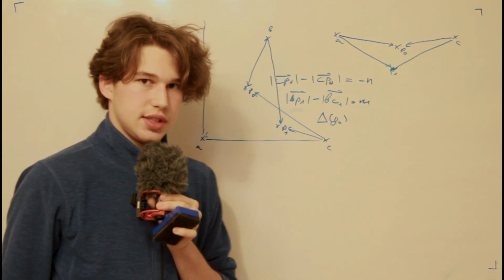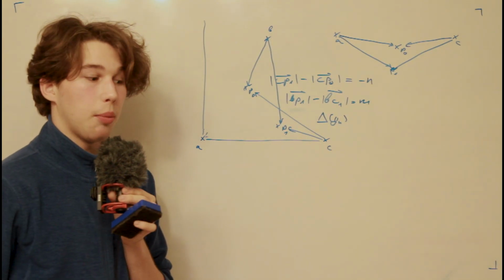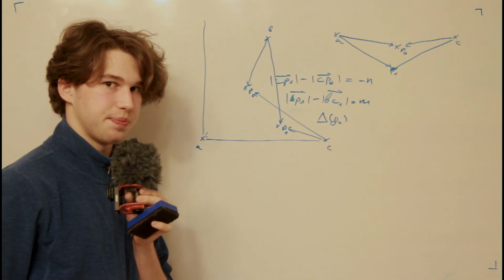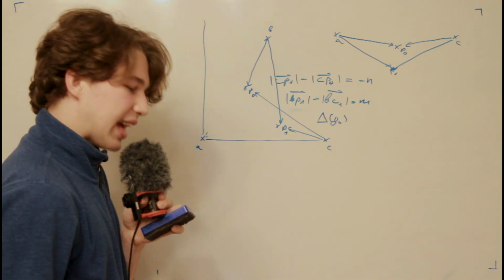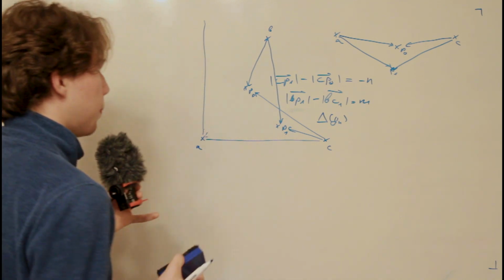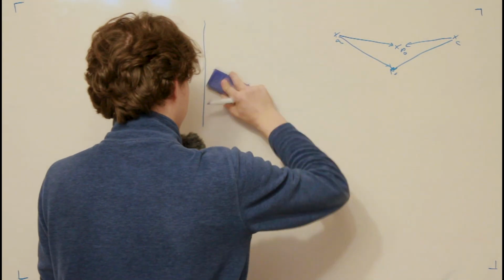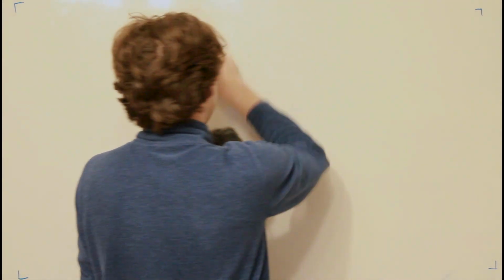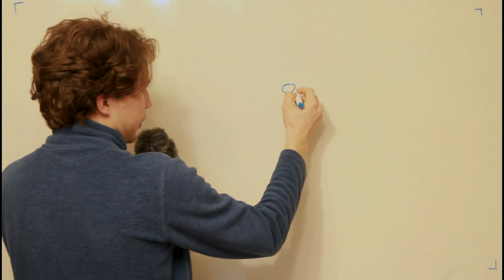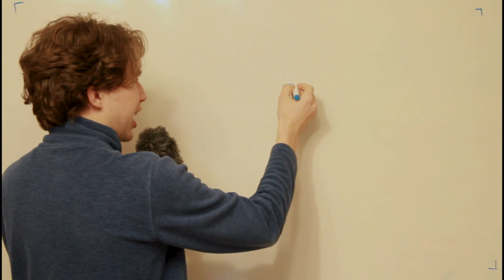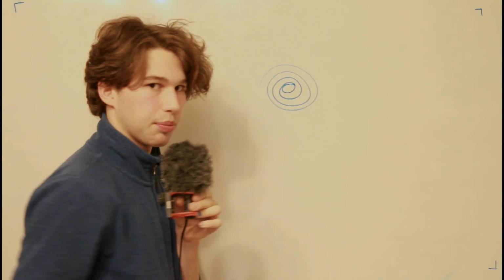So first, I thought, yeah, it's pretty simple because I always know how many steps my stepper motor gives. One thing I didn't account for was that the rope is winding. Let me show it to you. So if we have a cable drum and the cable starts winding here, the radius of this cable starts getting bigger.